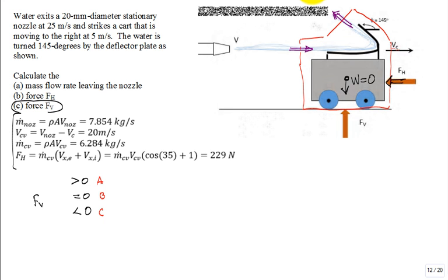All right. This is one of those tough things because we're going to talk about thrust in a minute, and it's on your perspective. You have a force, F of V, that's external to the control volume, that's acting on the control volume to push upward. Now, if you had no fluid flow at all and you had the weight of the cart, wouldn't F of V equal the weight? It would be like the weight down and F of V up.